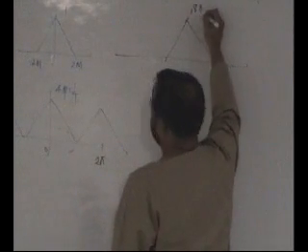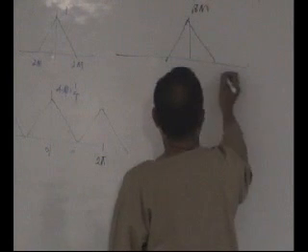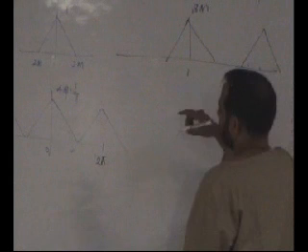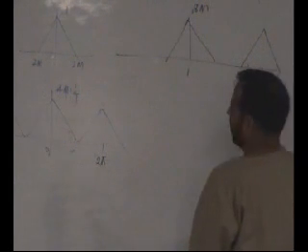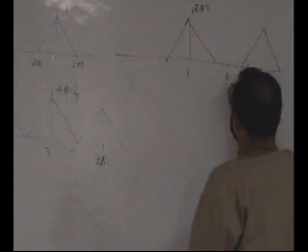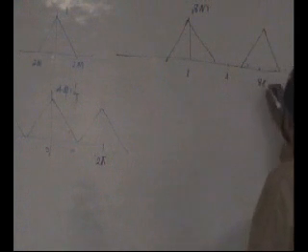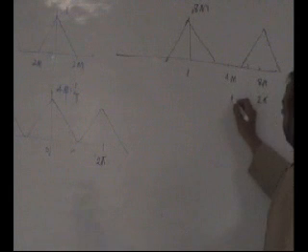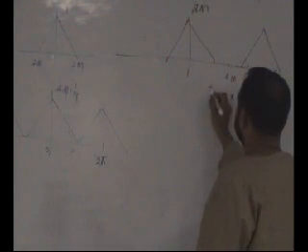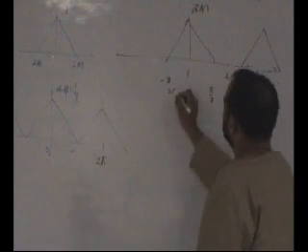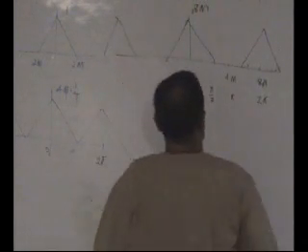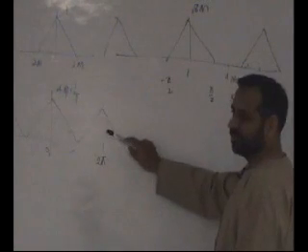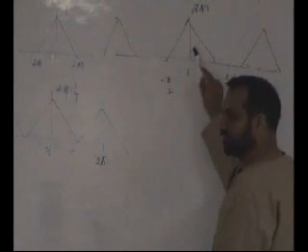It is 8 mega, right? And the next copy, if it is sampled at 8, will be at 8, so this will be 4 mega. So this 8 mega corresponds to what digital frequency? 2 pi, and this corresponds to pi, and this corresponds to pi by 2. So really this is what you want to do. In interpolation, you want this digital spectrum to change like this digital spectrum.